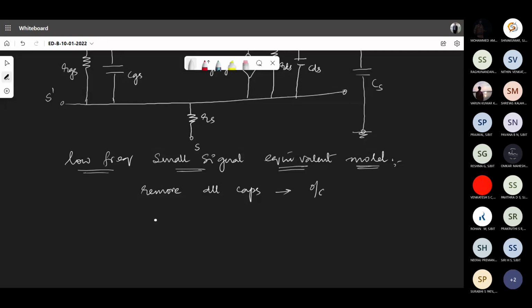The resistors indicated there are large resistance values because VGS is coming into picture now. For VGS equal to 0, if you remember the output characteristic curve, the resistance offered was very less. As and when you increase the VGS value, the resistance increases.